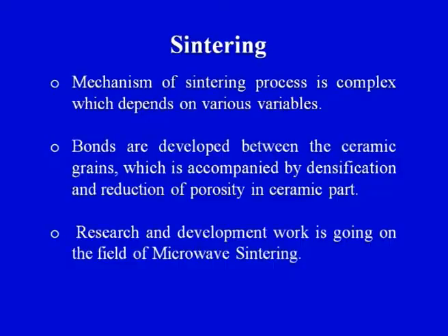This point I have already highlighted, that when the bonding takes place among the ceramic particles during the process of sintering, the density would increase and the porosity would decrease. So the bonding is accompanied by densification of the ceramic part, which leads to the reduction of porosity in the ceramic part. So if there are certain applications of this ceramic part where we do not want the porous structure of the part, then we can go for sintering to increase the density of the part. Otherwise also, sintering is an important step in the processing of ceramic parts.